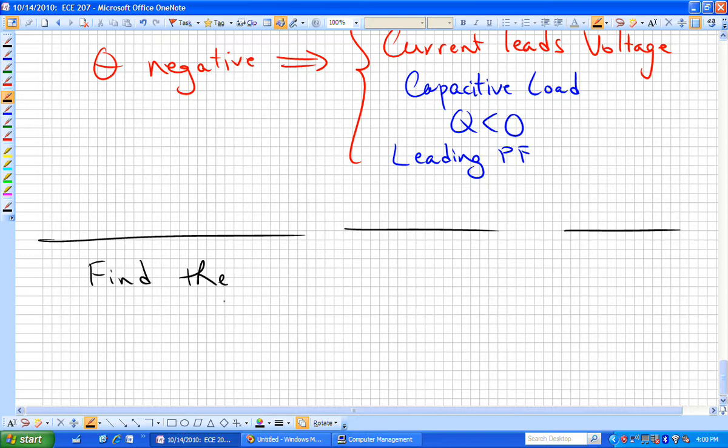So usually, as an industrial user sitting off from a substation and absorbing all this power, you look like a big inductor to the power company, which gives you a positive Q. You may get a surcharge or a tax on that because you are using a lot of apparent power for the real power that you really are consuming that's driving your loads, crushing your corn or whatever you're doing. Because of that, the power company is going to charge you more.